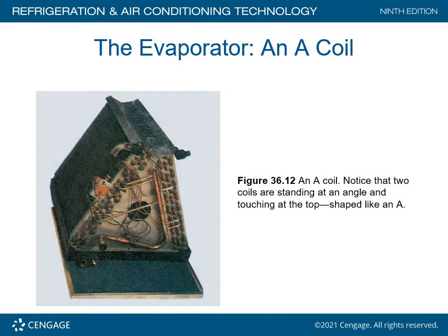Well, one of them, that would have been number 6, because this thing had basically 6 portions of the coil. And what I mean by that, basically 6 circuits. Instead of one circuit where the refrigerant flows through in and out, this thing was divided into 6 circuits. And the number 6 circuit had the copper laying in the moisture-laden pan, which you see here in this illustration.